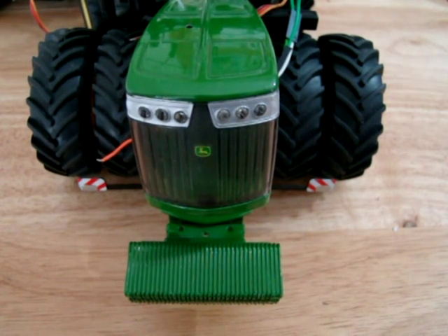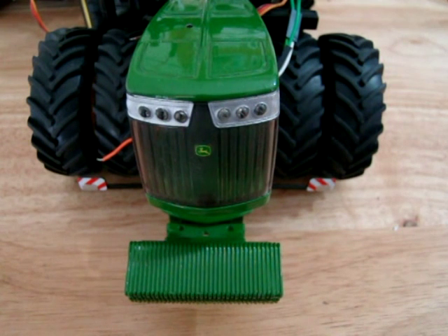Okay, so I've just uploaded the code for the green light, so let's test that they actually work. So our string again, our command this time is 0D and 00 for data because we're not using the data. But we need the 6 bytes, we have to send the 6 bytes or the tractor won't recognize it as proper code.